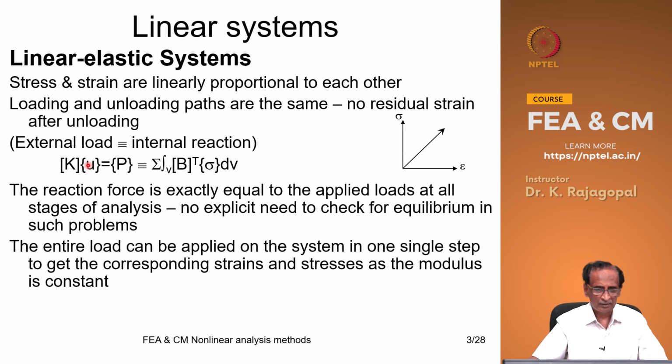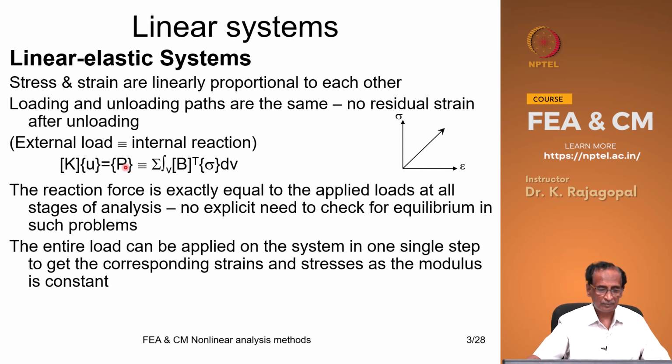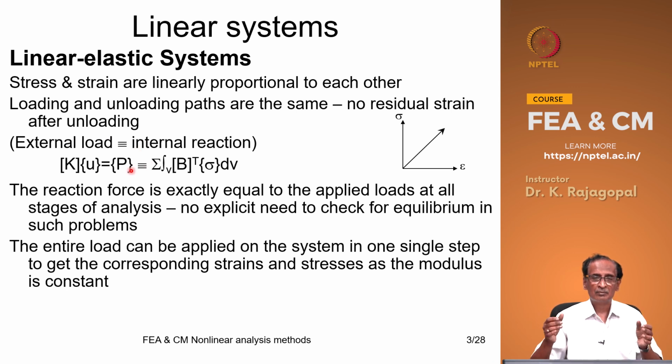forces. So in this case, in the linear elastic systems, we don't really need to check for equilibrium. It's automatically satisfied, because whatever stress is developed in the elements, they will be able to support that much stress, because there is no limit on the stresses that you can apply. And normally we don't write the right hand side in an incremental form, either as a dP or P minus reaction force, as we do for other systems.